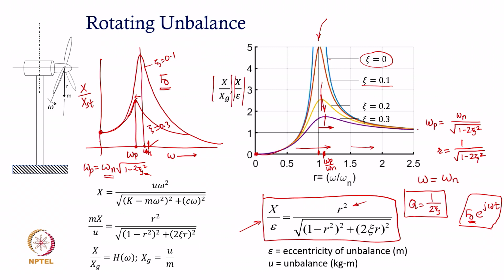And there is one more interesting difference here. For the constant amplitude excitation, as the frequency ratio increases, your response becomes smaller. Okay. So, x over xst will approach a very low value as the speed increases to a very large value, whereas you are seeing here that this response ratio is approaching what?